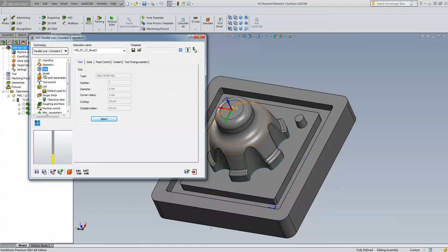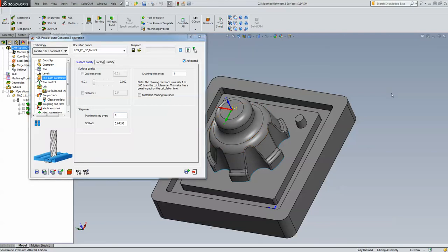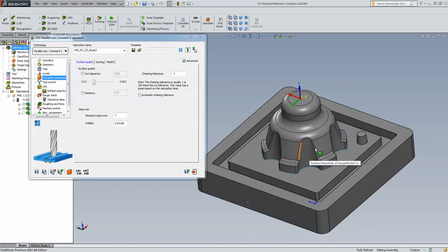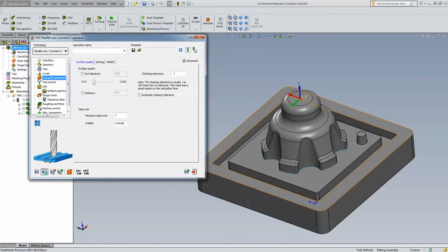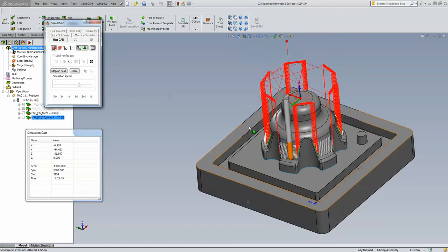Okay. Again, we have our levels, toolpath parameters, maximum step down. I'll leave it at 1 millimeter right now. Let me just do a quick save and calculate. Now, I know, by the way, there are gaps over here between these. But let me just first do a save and calculate, and we'll see the result that we have over here. You'll note the result is what I expected it to be.